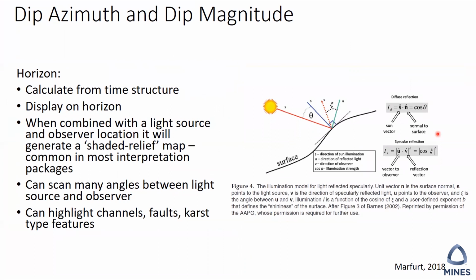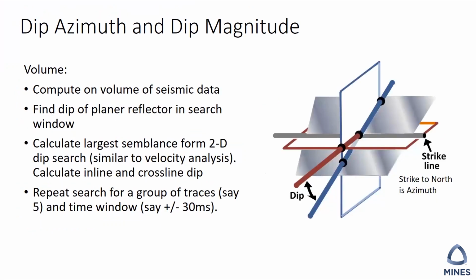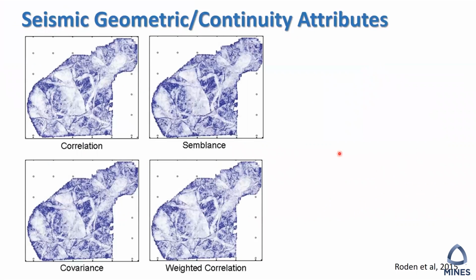if you have a surface, you can look at the dip and azimuth of that surface. This is another structural attribute that takes your surface and looks at the dip and the azimuth of that surface, where it is facing. This is another simple calculation that you can run once you pick the surface, and it could indicate different features on the data. Here it is showing, for this particular surface, the dip and the azimuth. And you can also calculate that and display that.